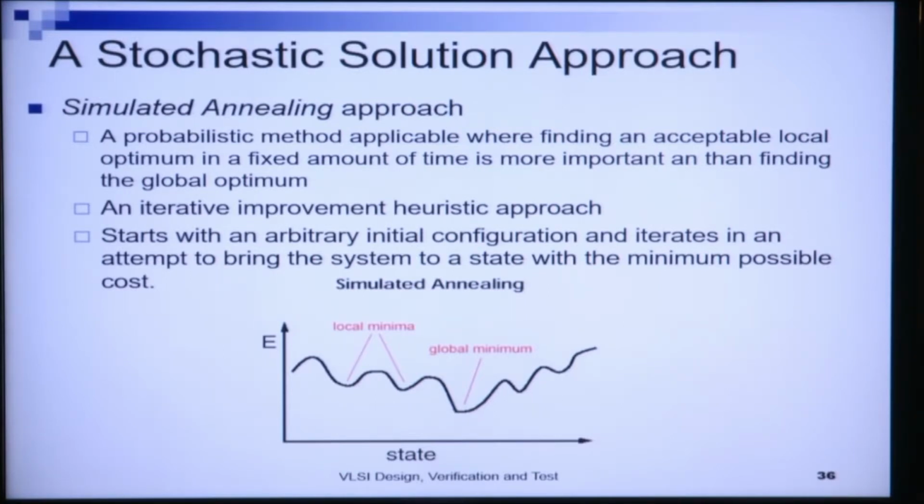So for a given choice of registers and functional units, I will have a certain mux cost, and therefore I will have an overall cost in terms of area, and each point on this line gives a solution in terms of the cost for that configuration. So each point on this line corresponds to a different configuration, in terms of which functional units have been allocated to which operations, and which temporary variables have been allocated to which hardware registers, right.